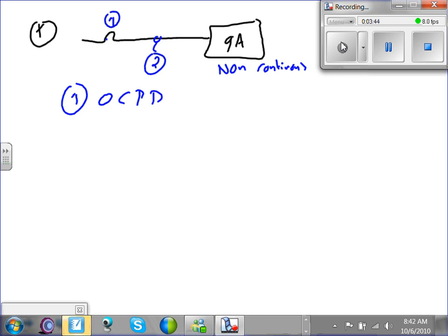Okay, so the overcurrent protection device. If it's non-continuous, all I have to do is take the 9 amps all the way to 240.6. If you have never been in 240.6, make sure you go there. 240.6 has all the standard non-adjustable circuit breakers and fuses that are made in the continental United States and elsewhere that follow the NEC code book.